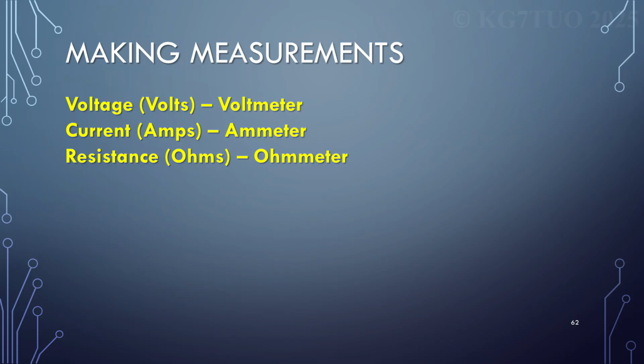Either of these cheap little things will do all 3 of those for AC and DC. Be careful what you set it at, though. Yes. So if you set this on DC and you measure a wall circuit that's AC, it's going to say 0. So those are multimeters? Multimeters. But that's not up there yet in yellow. But that's what they're called.